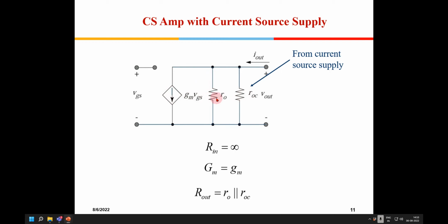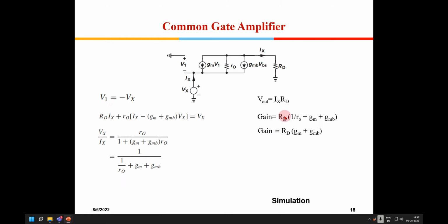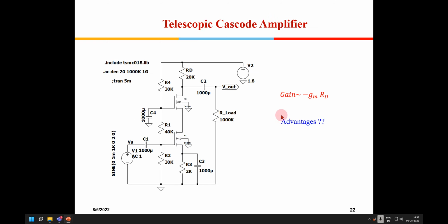If I make a Thevenin equivalent of this, it will be a voltage source and a resistance in series, right? So the output out here can be considered as a voltage in series with a resistance. And hence this top one will become a common gate amplifier. Is it okay? Yes, now got it.